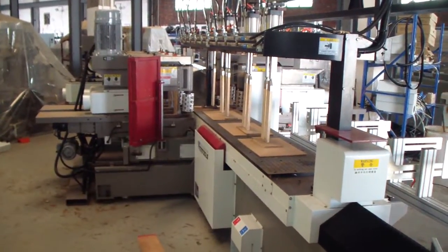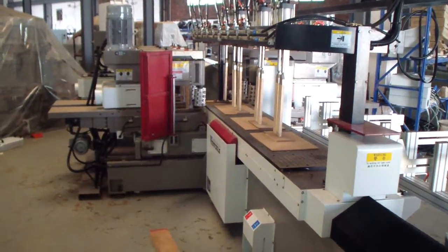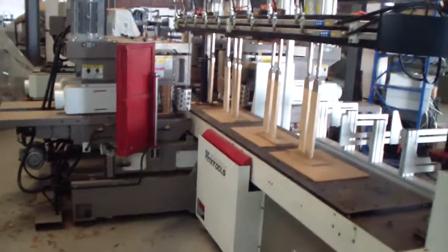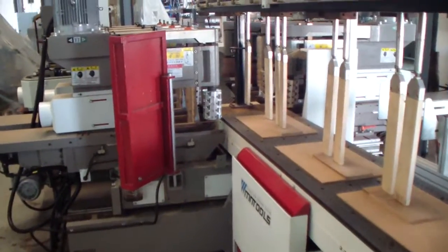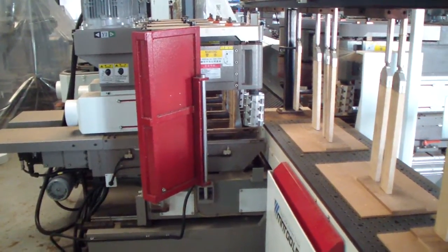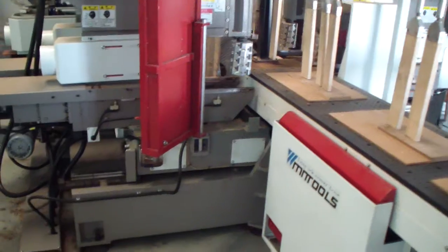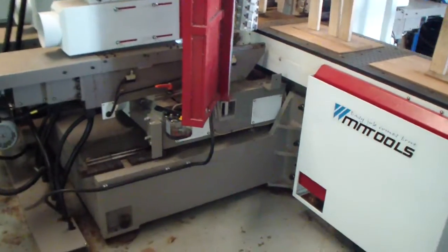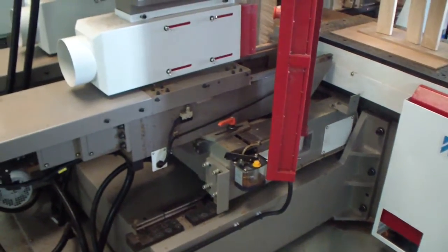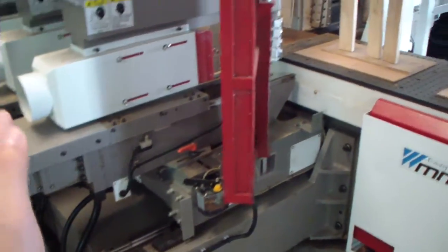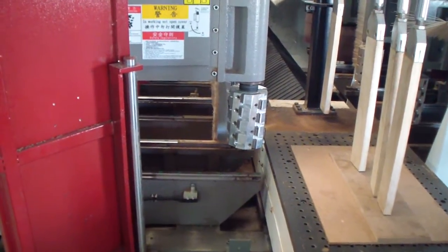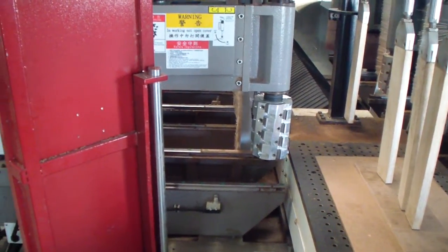In this video we will introduce how to do the torus calibration. Because when the cutters or sanding belt are changed, maybe it's necessary to redo the torus calibration. Especially for this machine, it's disassembled for shipment. After the user receives the machine and reinstalls this part, maybe the cutters have some little difference. It will need the torus calibration.